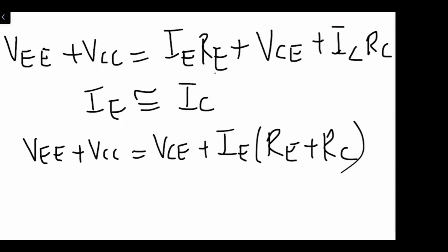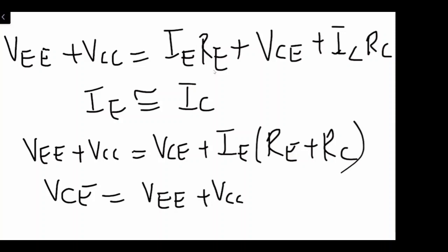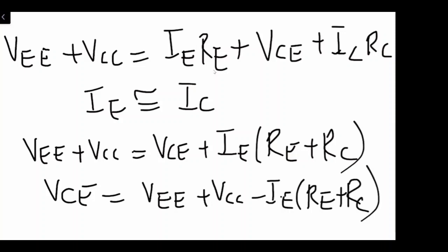Or I can say VCE is equal to VEE plus VCC minus IE times RE plus RC, right?